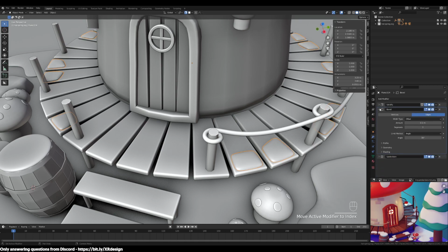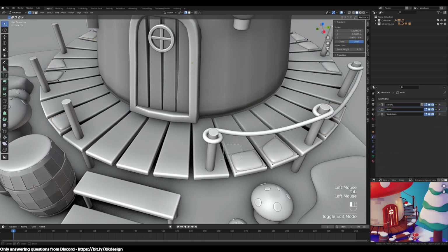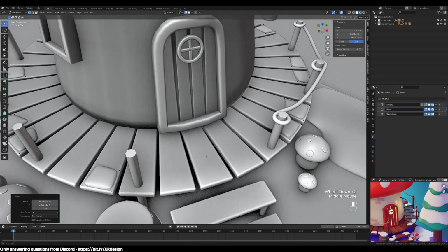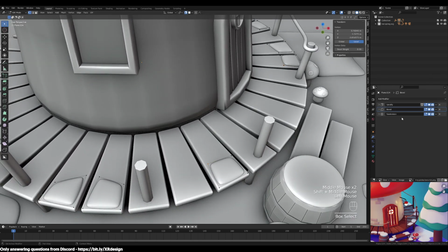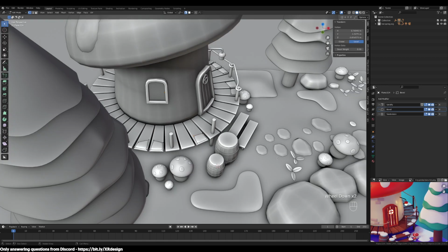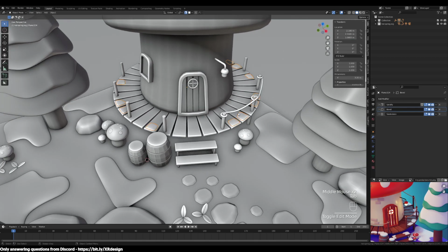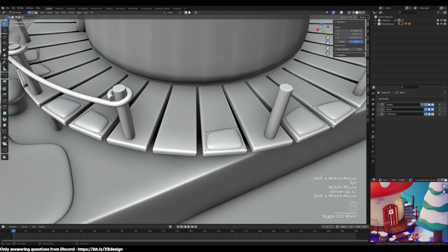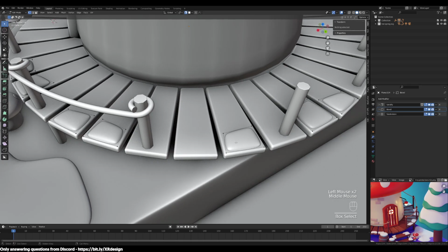So what you're doing is when you add the bevel before, you're just adding more geometry to this layer and then subdividing that. So that's a tip if you wanted to add more geometry to a subdivision. Just place bevel beforehand. It won't work in all cases, but for this one it does. And from here, I know Adam put a screenshot in the chat. You could add more geometry to this and tweak it further.